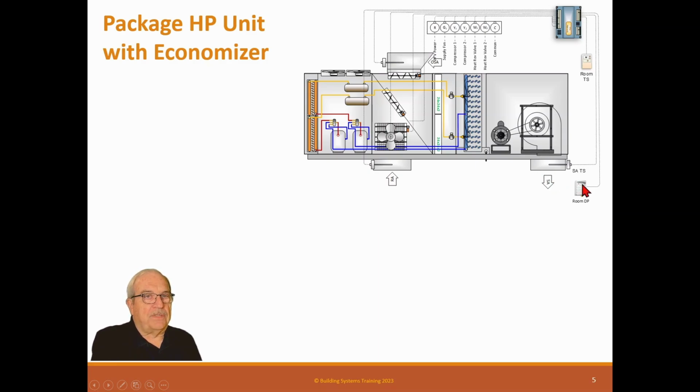One of the problems I've had before on these units would be on a VAV, but if it's constant volume, you should not have any problem if we balanced it properly. We wouldn't have a problem. This one actually has a room pressure sensor, so it could actually modulate this fan speed if it had a VFD to be able to speed up or slow down to make that pressure always right on the money. So you could do it either way.